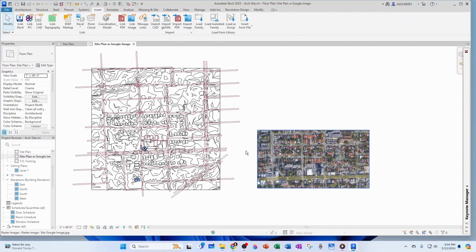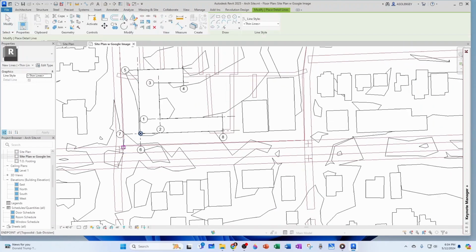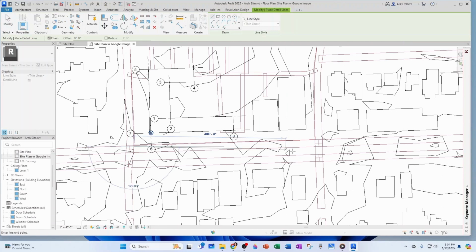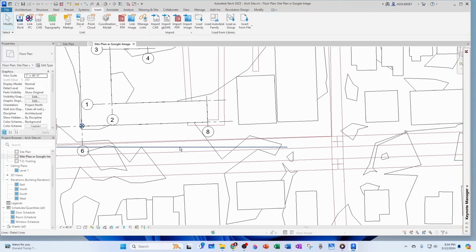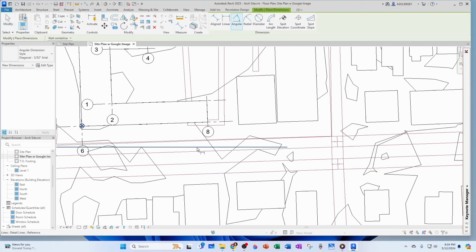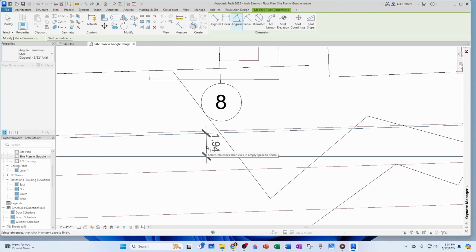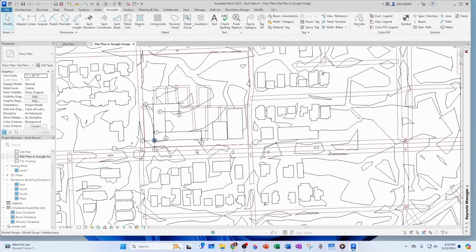And now something important to notice is that these lines here are not perfectly horizontal. Right? If I do DL for a drafting line and I come from here, you can see that there's a certain angle there, right? So one thing you could do is measure an approximate angle there. So you go to annotate and measure an angle from here to here. It's approximately 2 degrees, 1.94. So that's just something that could be relevant to note. I'm just going to delete this line.